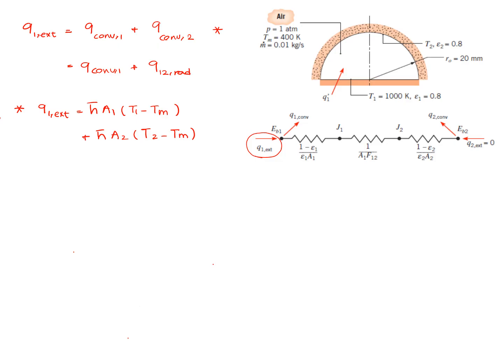I know that the temperatures of those two surfaces are not the same, so the film temperature is going to be a little bit different, and as a result my properties are going to be a little bit different, but then I don't have the temperature for surface 2. So for now I'm going to assume that it's the same film temperature, and I'm just going to assume that the mean temperature of the air is the temperature at which I'm going to pick my properties, and I'll use those properties for now, just for simplification, in order to calculate the h value.